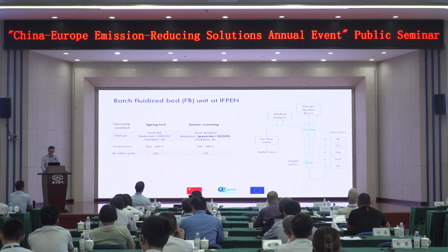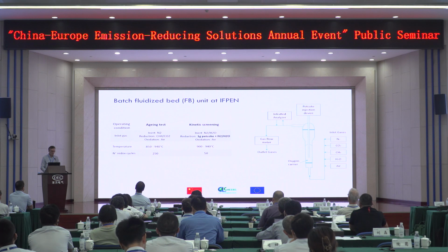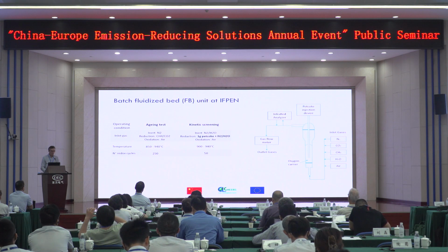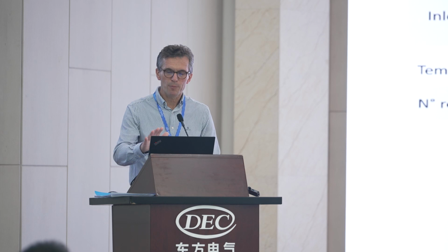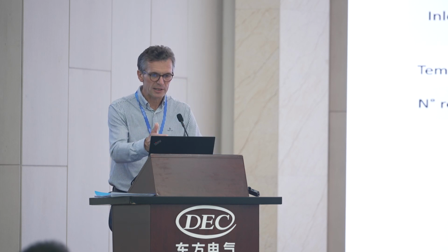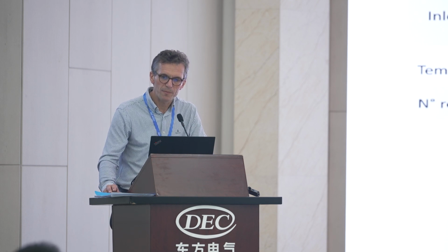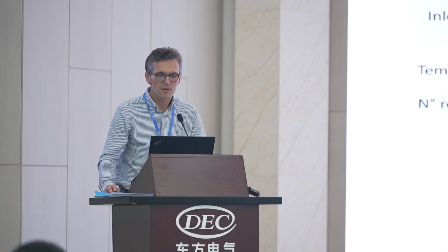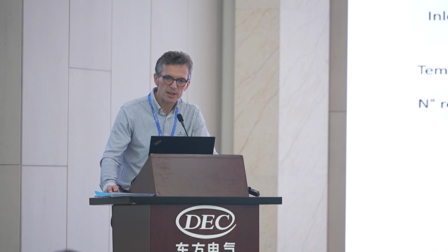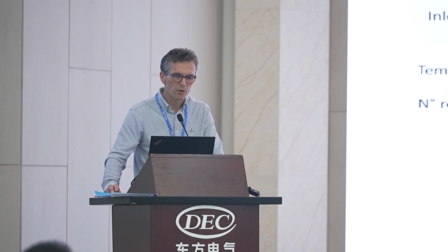Okay. So then I go a step up in the screening. We have this batch fluidized bed unit at IFPEN. Here we are still at the lab scale, but we are now approaching at least a solid fuel, pet coke. So we can inject pet coke into this chamber, where you have a bed of oxygen carrier. You can supply different gases. You can oxidize with air. Then you can supply different fuel gases if you do gas fuel cycling, or you can inject pet coke from the top and measure the outlet, at different operating conditions.